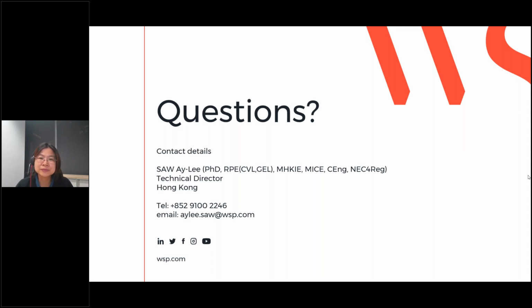The next question is, can InSAR be used to monitor long-term settlement at a facility? Yes, I think so, but it depends on what kind of facility you are referring to. Bear in mind that if it's a window, there are refractions. Bear in mind that this is a kind of radar, it is a wave. So for water it is not working, and a window or a concrete surface is different. Also bear in mind that if your building is higher than the ground,